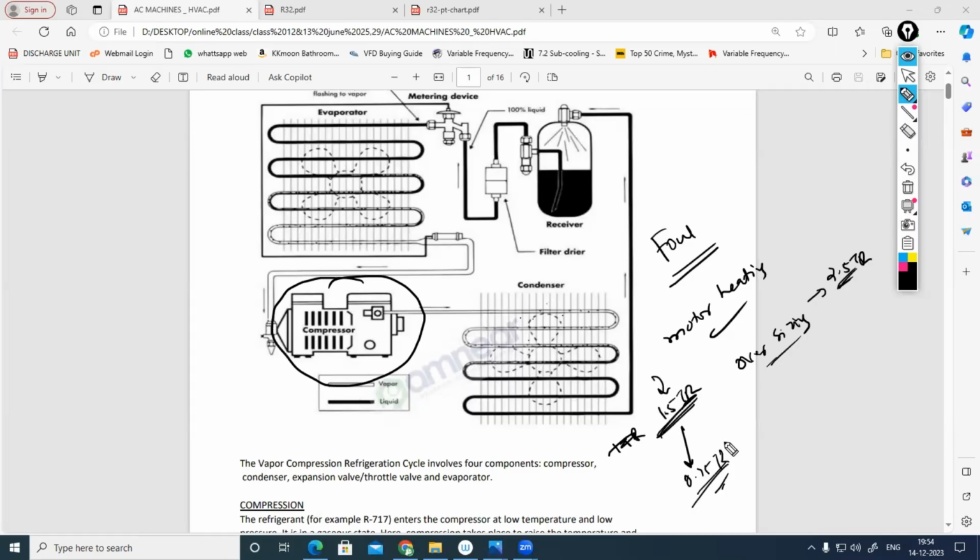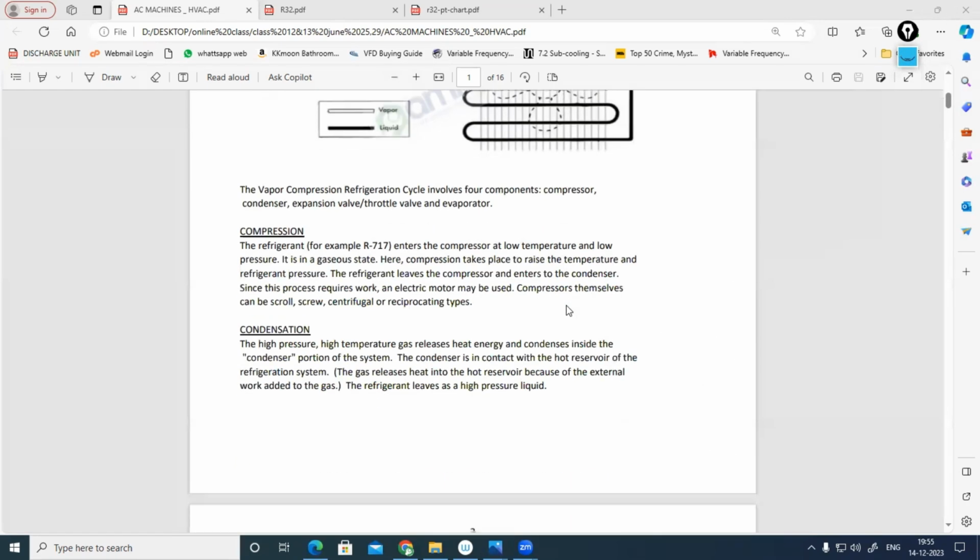In both cases, the on-off cycle of your compressor is high, meaning whenever your AC motor starts, it consumes starting current, which is 2 to 3 times, or sometimes 4 times, more than the running current. So excess starting current means your motor will heat. In the same way, if you are undersizing it, your compressor motor will be continuously working. Since it is continuously working, the motor, armature winding, everything will heat up. Your motor may get damaged. Even if we have oil and everything inside, motor heating is an issue. Okay. So coil fouling and motor heating are all issues.